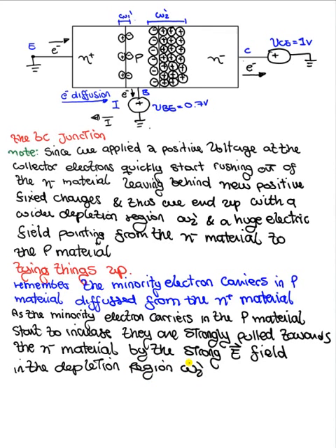Okay, and then this collector current is orders of magnitude greater than the base current, and is what makes BJTs be seen as current controlled amplifiers and current controlled current sources, right? This is why the bulk of the current goes from collector to emitter, and is due to that effect. So let's write that down.